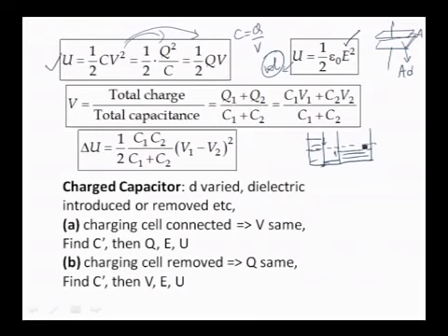So it is by common sense you can see that the common level that you get should be between these two. So that means if you have V1 as some 10 and V2 as some 20, this common potential cannot be less than 10 or cannot be more than 20. It has to be between: this 10 increases, 20 decreases, and finally you will get some equilibrium value, which is the common potential. So only by that concept, maybe sometimes that is enough to choose the answer.